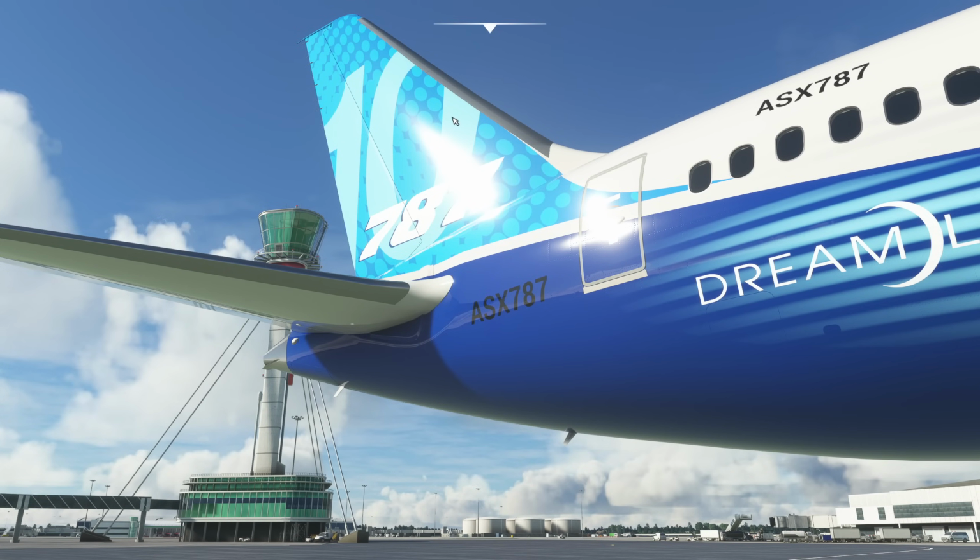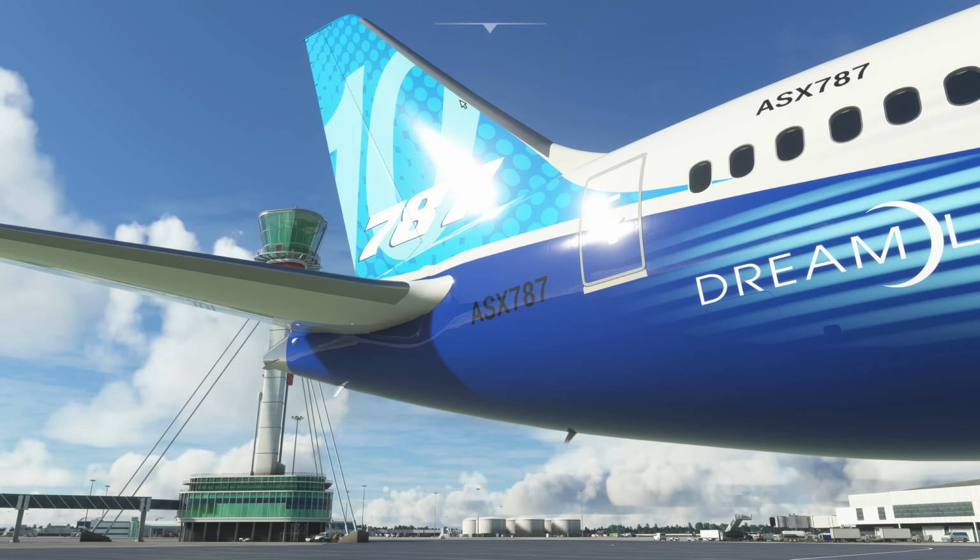This way, during takeoff or any sort of gust that would evoke a turning force on the tail, so a gust of wind striking the tail on one side, the static ports sense this because they can feel that change in pressure. There'll be higher pressure on one side, lower on the other. Now that would cause the airplane to rotate, to try and turn into wind like a weather vane.